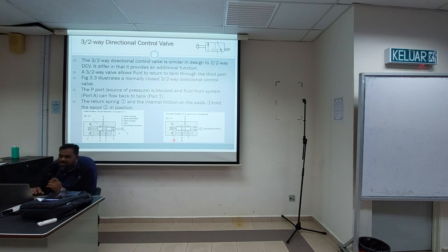This one we usually use in time delay valves and normal operation. Even the normal push button in a circuit we attach with a 3/2 valve. The 3/2 has only one working port. If your application needs just one port to control, you can consider it, no need to buy a 4/2 or 5/2 that has many ports and use just one port. Of course, more functions means more expensive, so you need to select the valve properly.